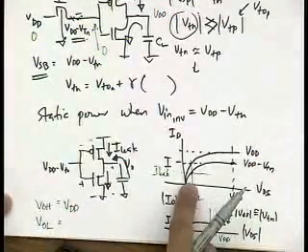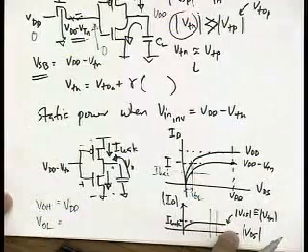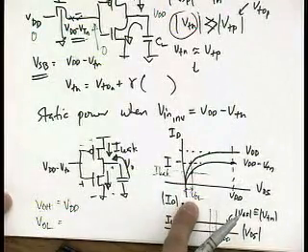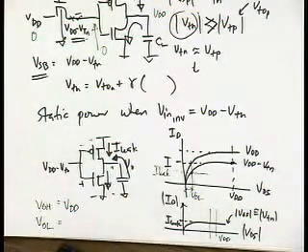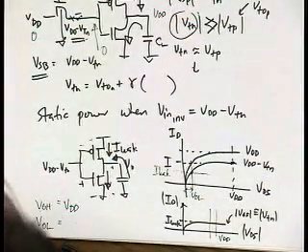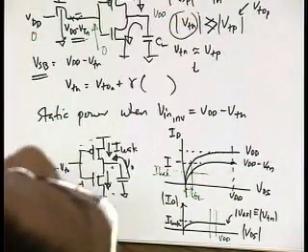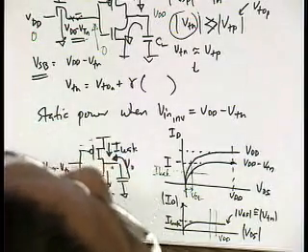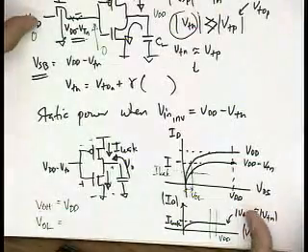But the idea is you can solve it exactly. If you know the leakage current from the PMOS, you can get your output low voltage for the NMOS. Any questions on that? Questions? If we're going too fast, slow, we can speed up. Good.